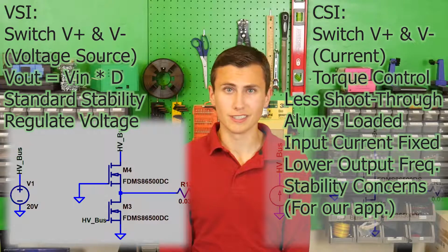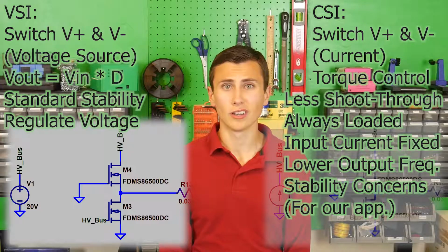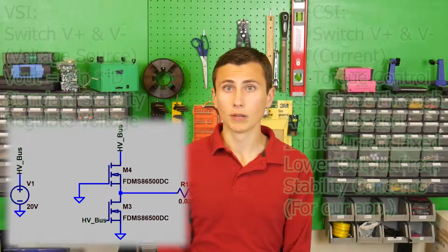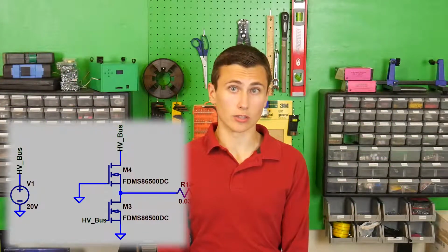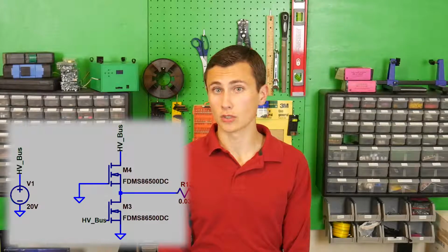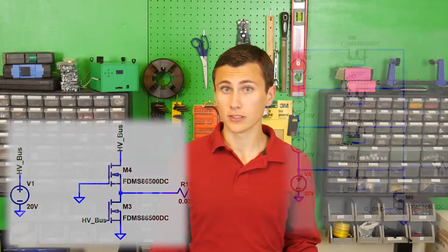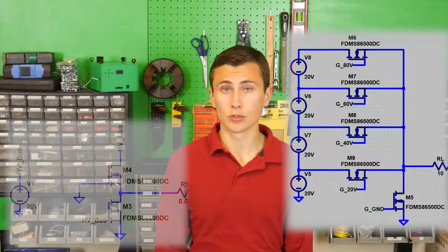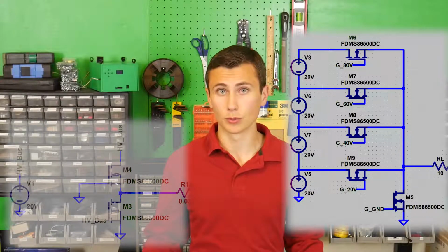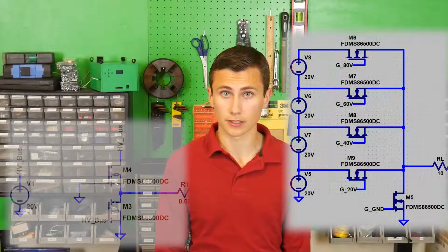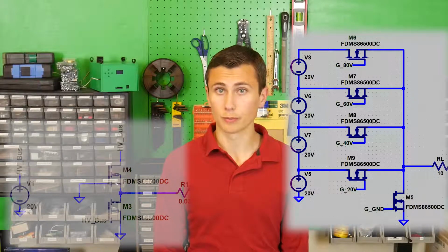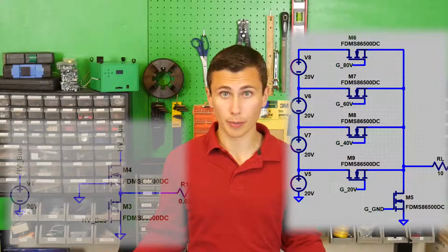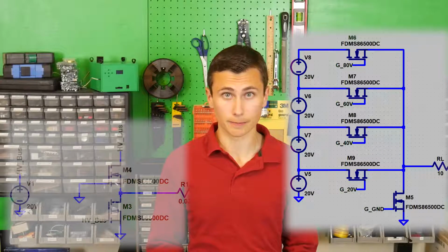They just switch between VCC and ground to produce an output voltage? Well, they can. But if a person wanted to reduce switching losses, reduce electromagnetic emissions, or improve efficiency, multiple DC voltage levels can be used to reduce the switching losses and reduce the required change in voltage per second. The switching losses are reduced because when the switch first turns on and begins to conduct current, the voltage across it will be reduced, and so will the power dissipated in it.